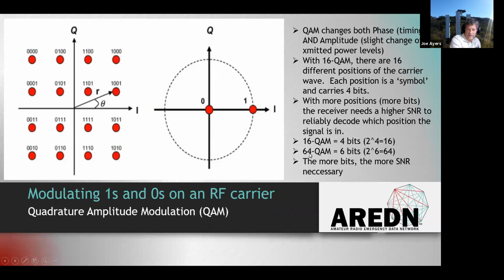So 16 up to 64, and it could be even more in the AC specification. That's going up even higher than 64. We'll see that in 802.11n, but you'll see as they keep developing these standards and improving them, they keep making them more and more complex, for more rate and more efficiency of the channel in transmitting.